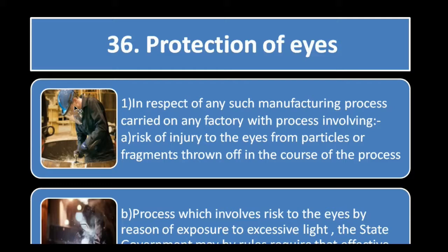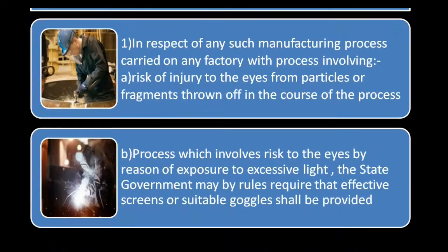So adequate precaution has to be taken, such as a face shield worn in case there are a lot of particles spattering outside the grinding area. In processes such as a drilling machine, safety glasses are mandatory so that the particles or fragments do not enter the eye.